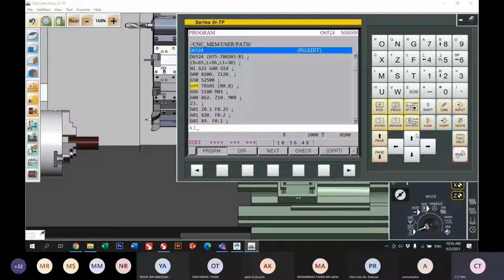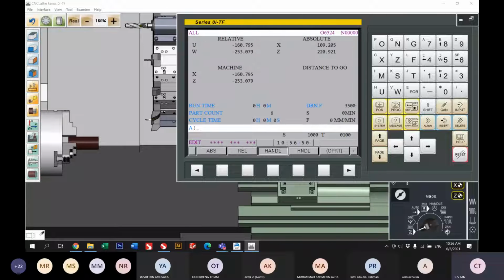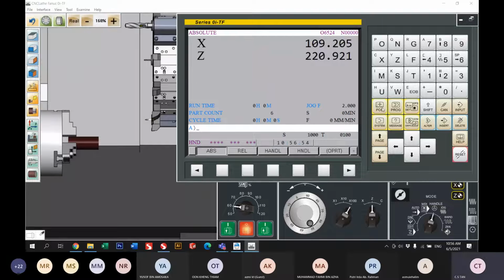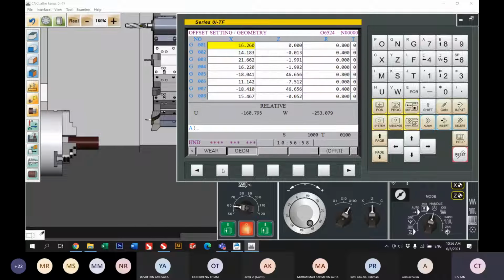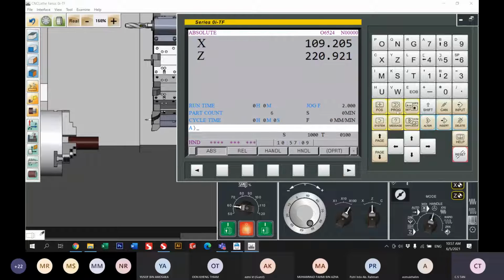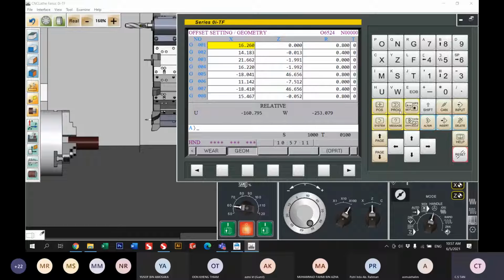Okay, so for Fanuc it is quite simple to remember. Normally when we do a job, most of the time we will refer to positions and also offset, because we want to do the tool length compensation settings. So it's most related to our positions. So usually in this mode, we will only use position and offset most of the time.